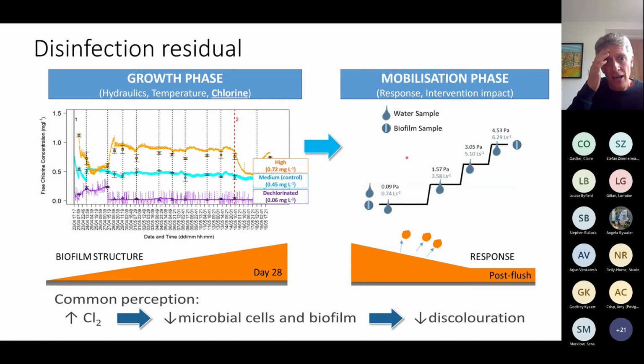One of the other important environmental conditions that we manage and look after is the chlorine residual. So we add a chlorine residual to our treated water as it goes into our networks, with the idea of trying to limit regrowth in the bulk water, but also protecting against contamination. So what we did in this case was to put our normal Sheffield tap water in with our residence time getting us about 0.5 milligram per litre.